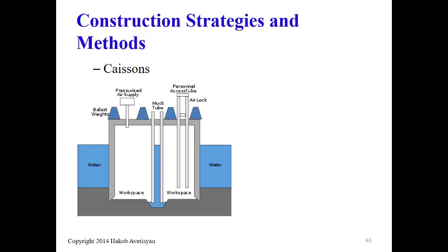So whenever you are planning such work, you have to be concerned about the timing of one shift in that condition. Just a couple of hours is about the most you can leave a human in that pressurized system to operate. So you have to have multiple shifts and multiple personnel to keep the work going. Otherwise, you will have interruptions, which will affect your productivity and slow down the completion time of the project.